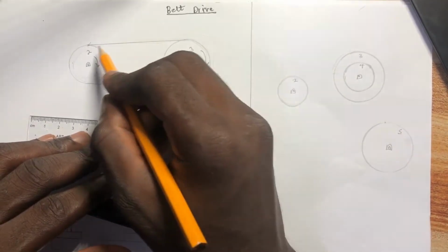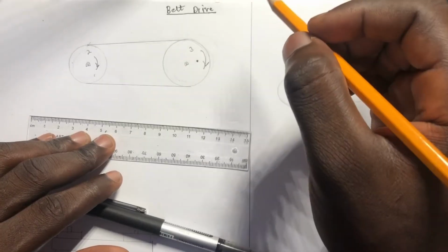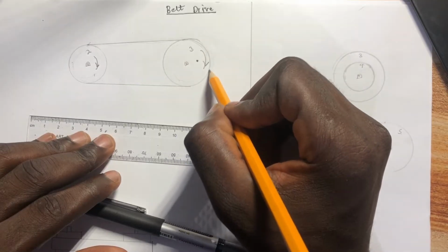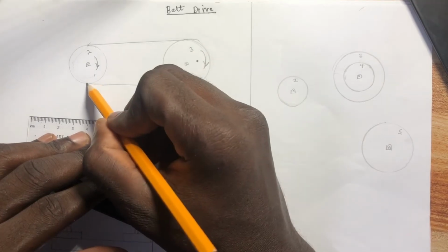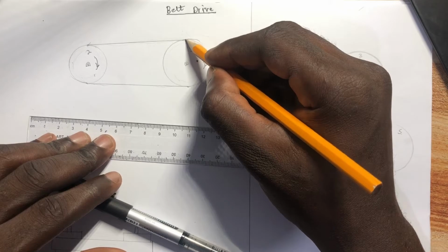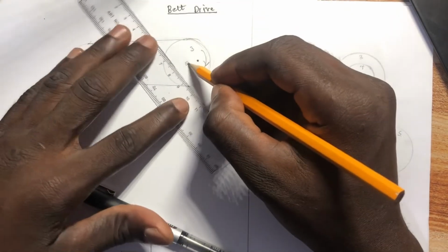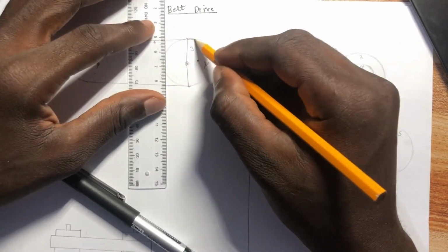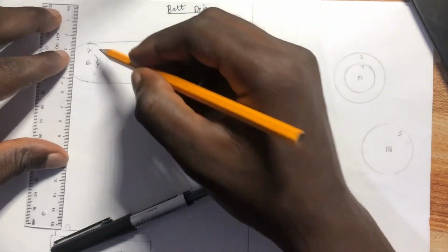Now, before I go to the velocity aspect, I want you guys to understand what we mean by wrap angle. So this part of the belt wraps around pulley 3 up to this point, and then it leaves pulley 3. When you get here, it starts wrapping pulley 2 from this point up to this point. So it looks like we form a chord from this point up to this point. So the angle subtended at the center by the chord here, which is the angle here, theta, is what we call what? Wrap angle.